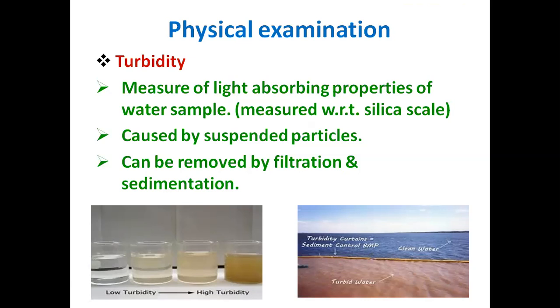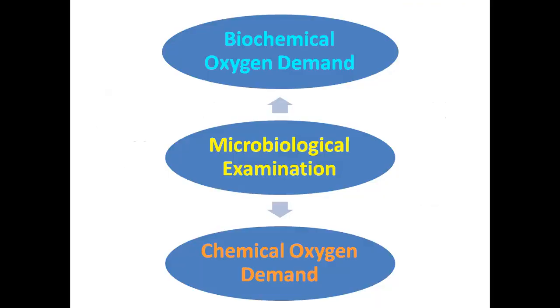If you allow this water to settle down with a simple gravitation technique, the solid compounds can be filtered or simply removed. Okay, so how to remove? It can be removed by filtration and sedimentation. This is generally caused because of suspended particles. This is the last of the physical parameters.